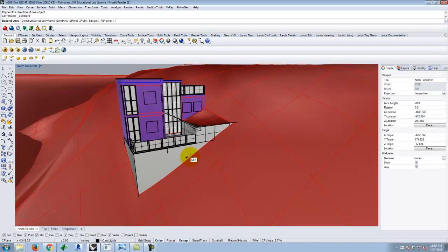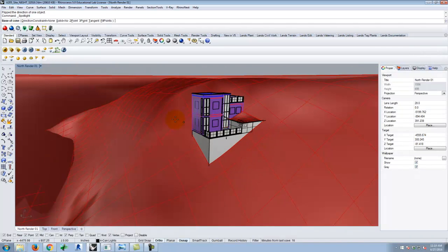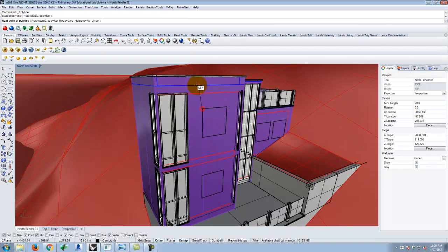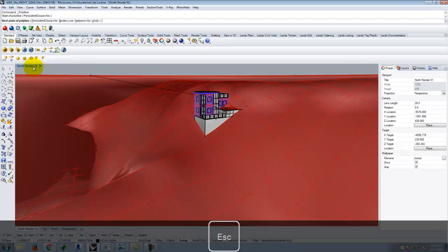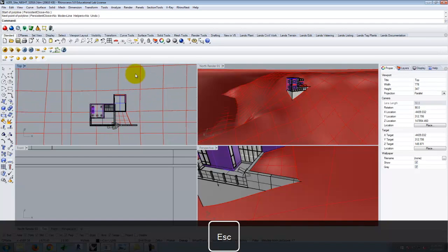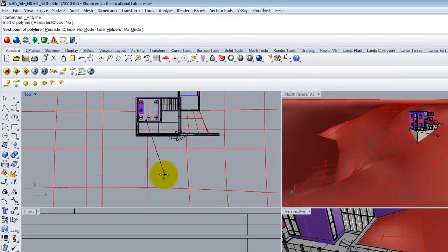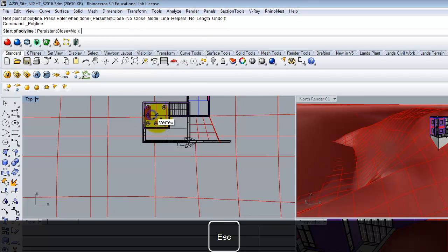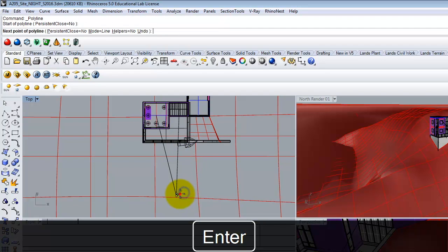So let's create a spotlight. It's hard to necessarily pick exactly where it's going to go. So before I do the spotlight, I'm going to get a general line of a target that's pointed out here in space somewhere. So let me turn off ortho. It actually might be easier to do this in top view. So if I had a line, maybe from right about there, maybe one more.